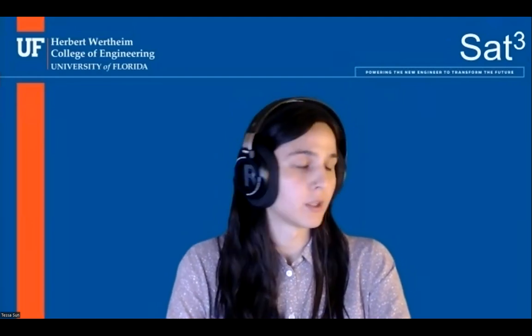Sorry, I'll answer this one. That X pattern was because of weight requirements. When we first designed our initial design, without including several other features, it was already at like 5 kilograms. So we had to very quickly find places where mass was not explicitly necessary that could be milled out, and the door was one of the more obvious ones. And we also did confirm that it is still strong enough to withstand the loads that it would be subject to.